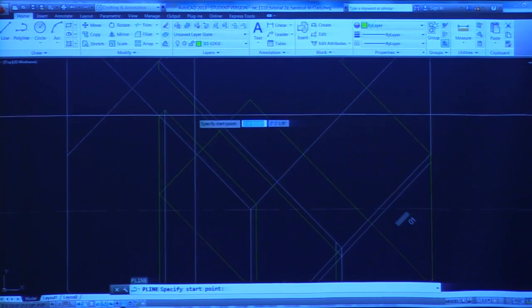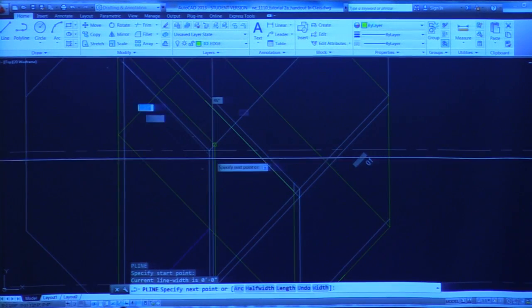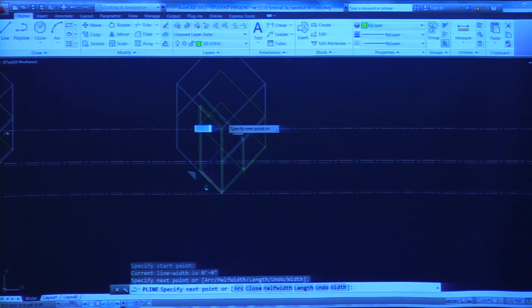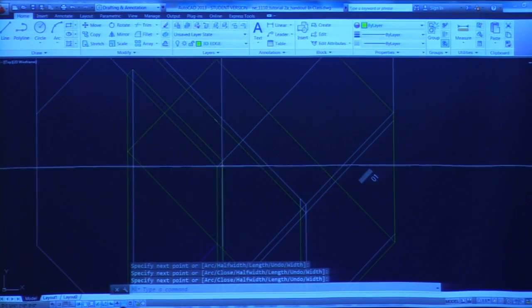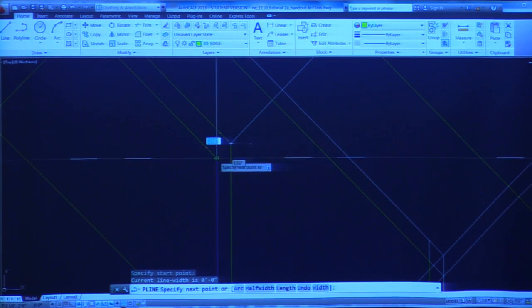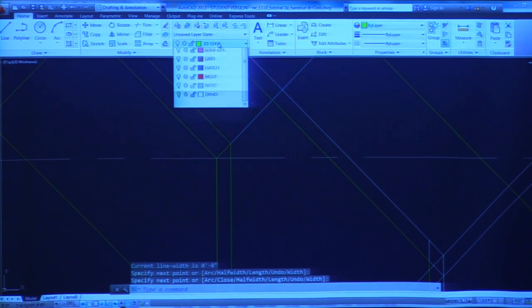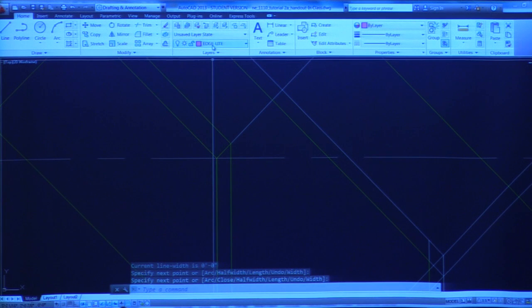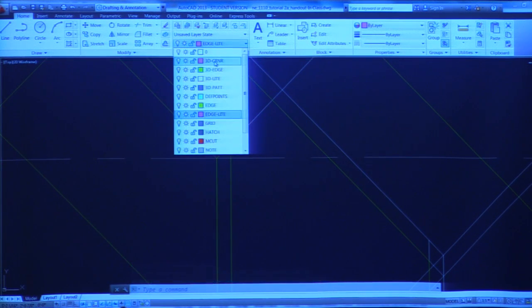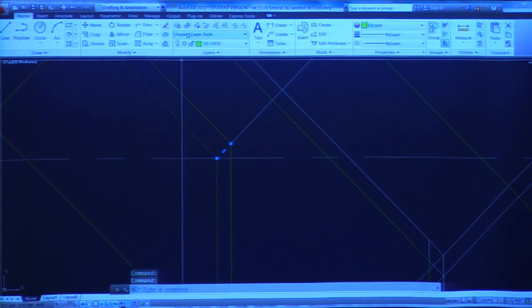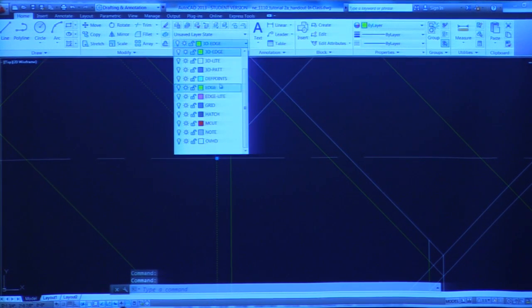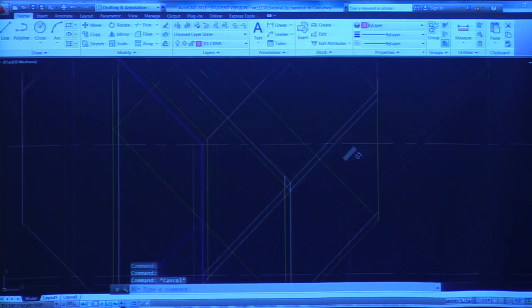Because I want to wrap this little part of the tutorial up, I'm just going to finish up with my line weights. This is my corner line weight. Hopefully we've gone into a little bit of that with you in studio. And I see I didn't switch my layer, that's not the right one. 3D corner, there you are. And so this is when things are coming closer to me, that's kind of the next step down in line weight. And you can see I'm changing layers by just doing that.